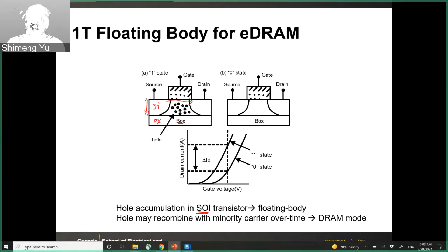If you have large current, the electrons may transfer the collected energy from each other, so one electron may generate more electrons. This is called the impact ionization process. As you generate one more electron, you get one more hole, because the electron and hole will be pairs. Electrons will be collected to the drain, and holes will be left over in the substrate.